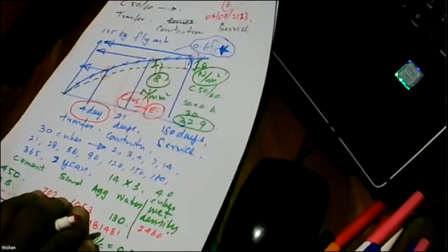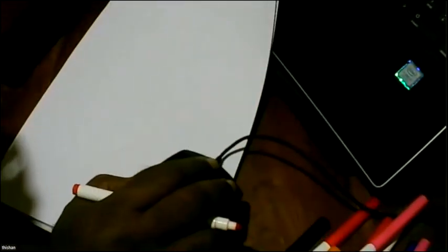The only thing is, you again have to use the correct E value applicable to that strength range. That way you can easily work out the stress history for the pre-stressed beam that you are designing. And with the stress history that you expect, we can optimize the designs to a great extent, right? So that's the way you have to look at it. So that is the concrete strength, the concrete technology part. And now I can move to the next layer.